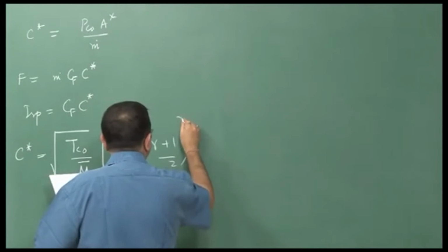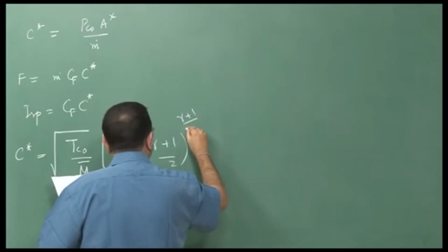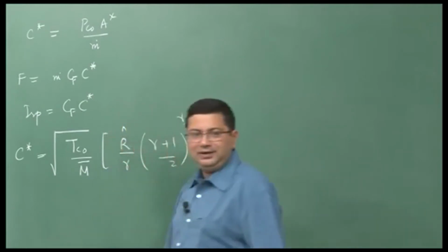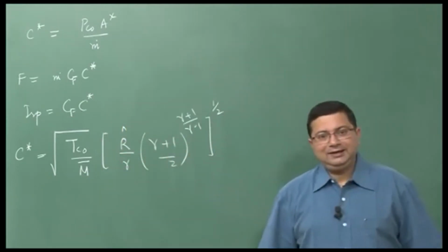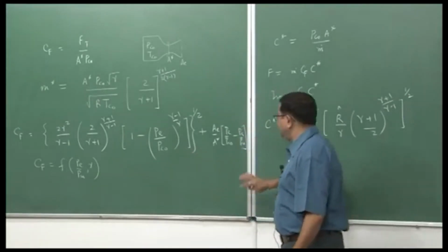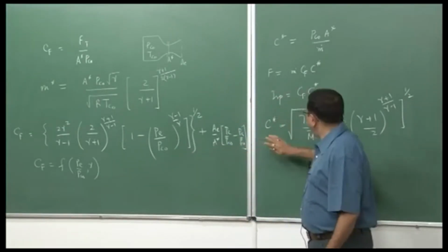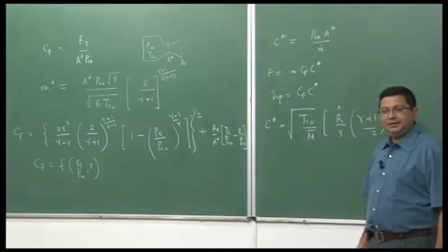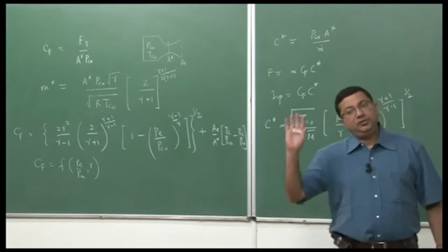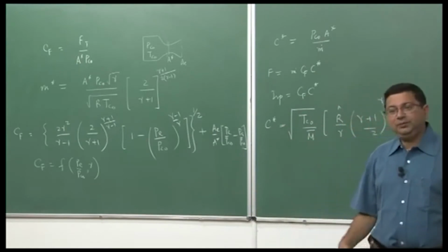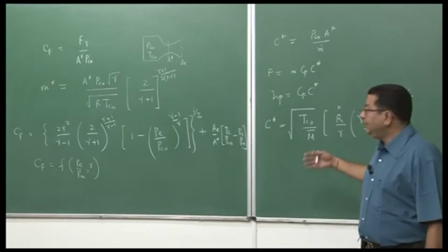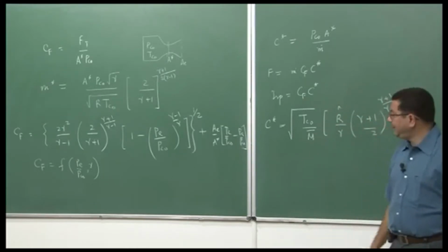So, we have shown that in the last lecture, and we had stopped here at the end of the last lecture. Now, we have the two expressions for specific thrust, the thrust coefficient and characteristic velocity. We see that the ISP is the product of these two. From our mission requirement from the very beginning, we have been saying that we want to maximize the ISP, so that our equivalent velocity will be higher.